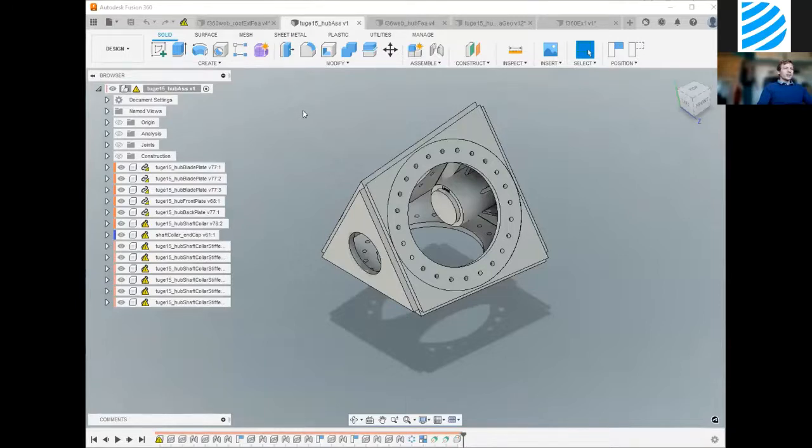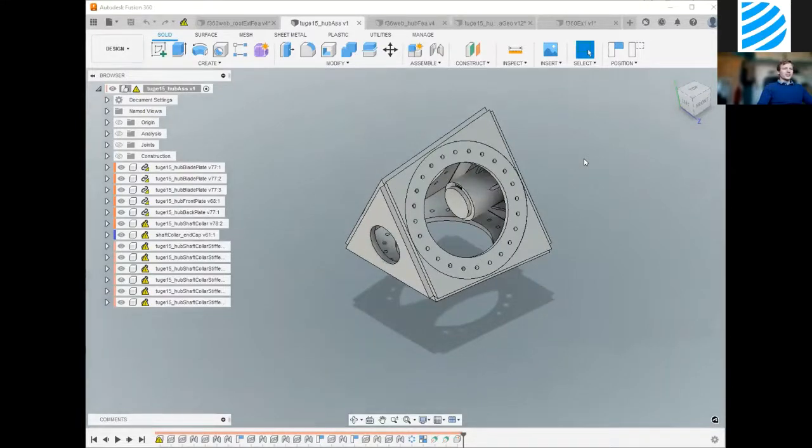Well, as I mentioned, usually I go with the thickness of the part if it's a hollow cross section or a plate. Sometimes that can be an issue if it's a very long tube, for example, and you have too many elements. But in that case, the smarter thing is to chop your tube up into smaller sections. But overall, as I said, with parabolic elements, I go with the plate thickness. But the best practice really is to do a bit of a convergence study, so you can run your simulation with a few different scales of mesh and check that the stresses are converging. So I hope that helped.